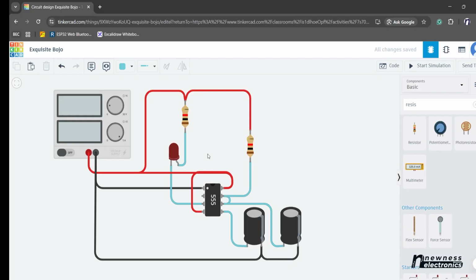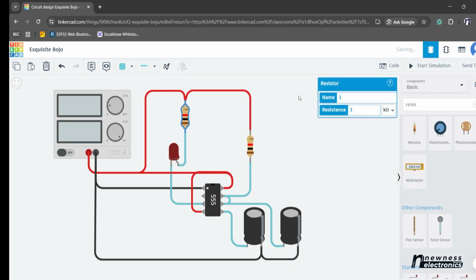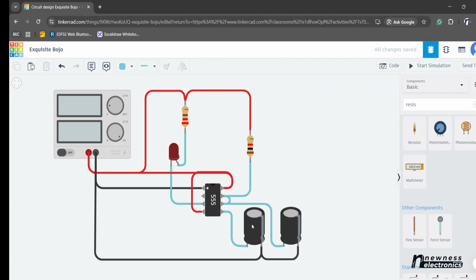So that's the circuit. Now, what are the values that are necessary to operate this? For this one, if you are using a 5 volt supply, your 220 ohms will still be okay. For this one, it's recommended 1 uF is okay, or 10 microfarad, 16 volt is okay. But now, what are the values of this resistor and this resistor?